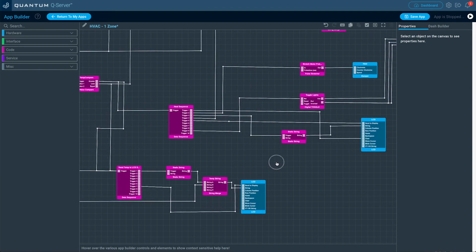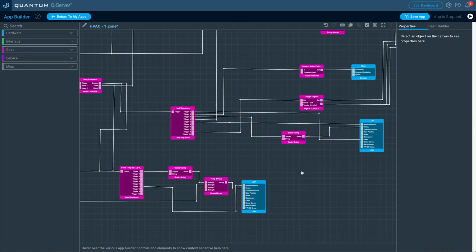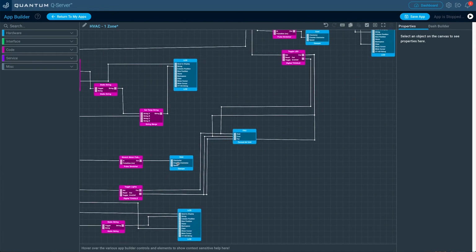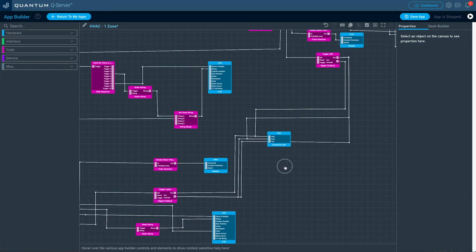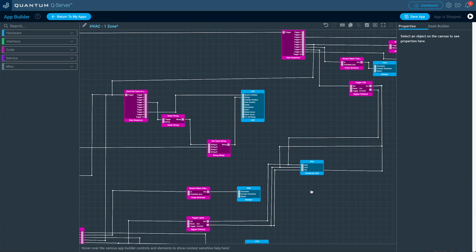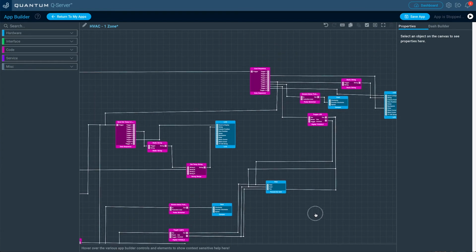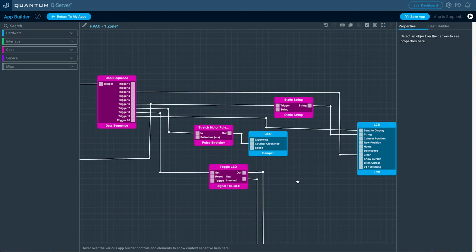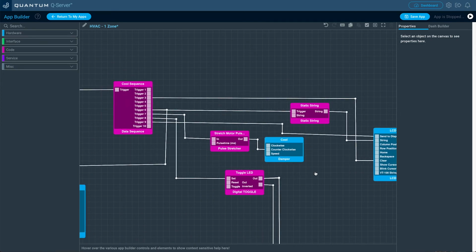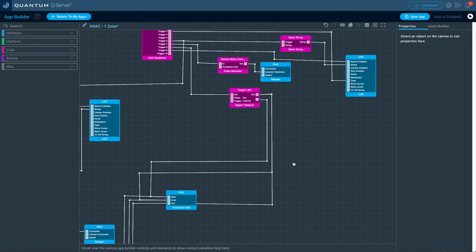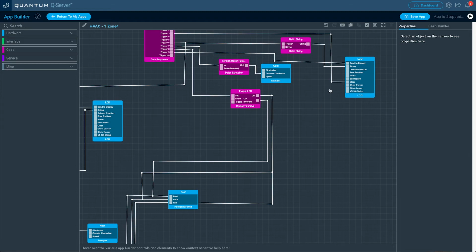To the right of this, you can see the logic that is used to enable heating, which essentially closes the damper and turns on the red LED. The information is also sent to the blue LCD hardware object again. Above this group of objects, we have the logic to enable the cooling, which essentially opens the damper, starts the fan, and turns on the blue and green LEDs. The information is also sent to another blue LCD hardware object again.